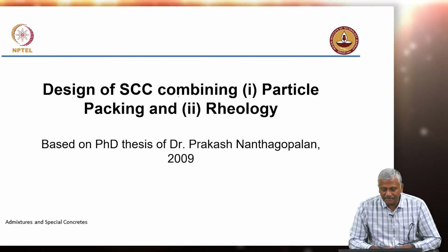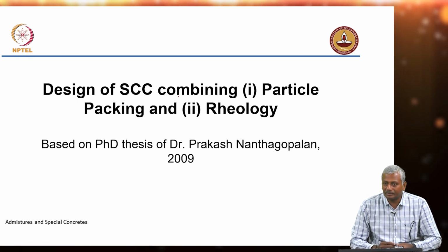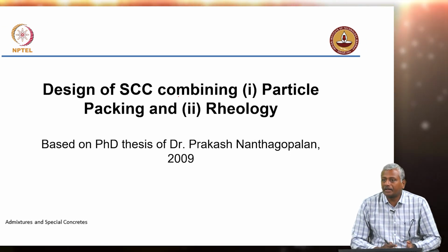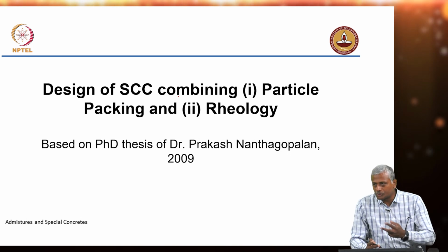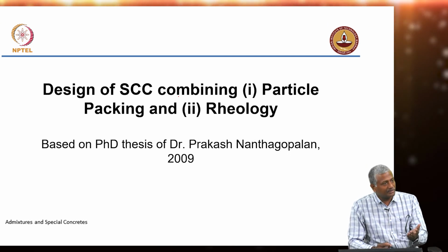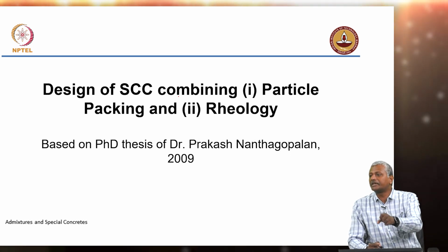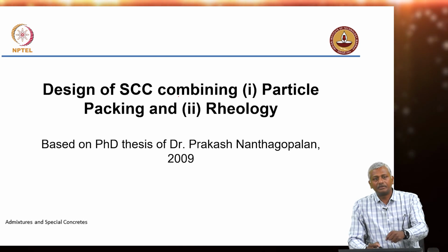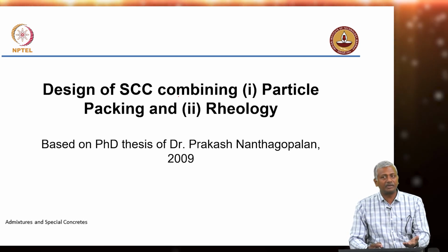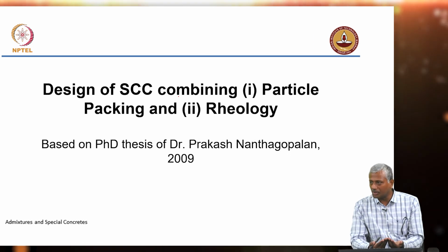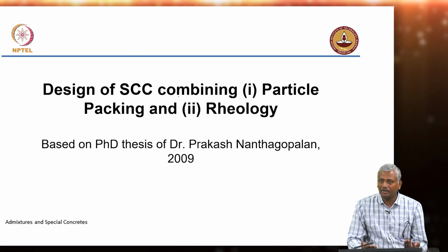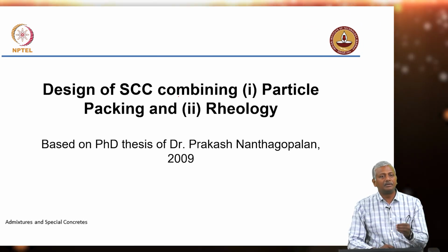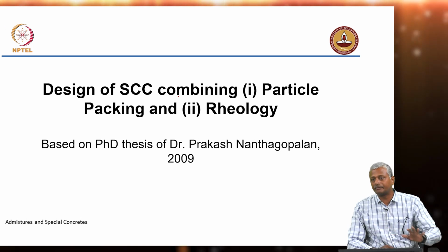Okay, so now let's come to this example of the work that was done at IITM, where SCC was designed by a combination of particle packing and rheology. Ultimately those two things we need to address, right? We talked about the fact that in any high performance concrete, if you maximize the aggregate fraction, you minimize the void content, right? What you have to do then is, based on the void content, decide on the amount of paste that you need to get the required workability, and the paste itself needs to be designed with an optimal rheological characteristic to have the maximum flow possible.